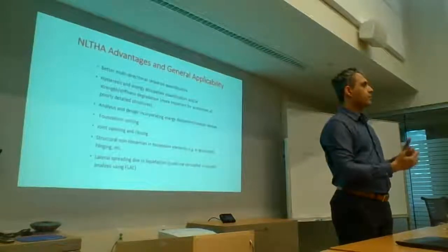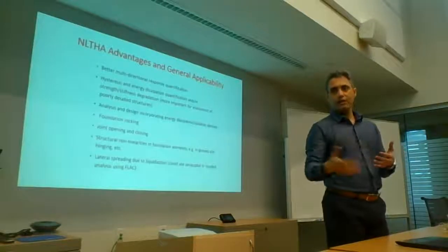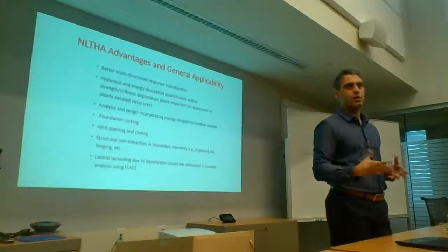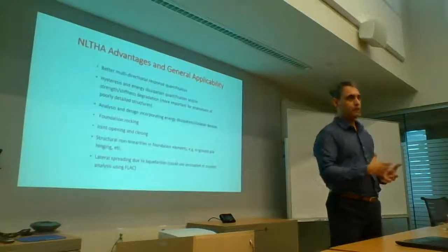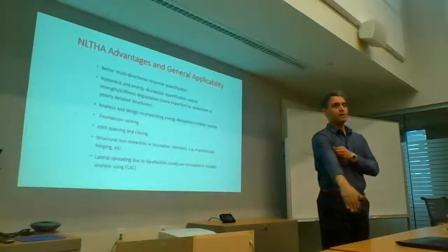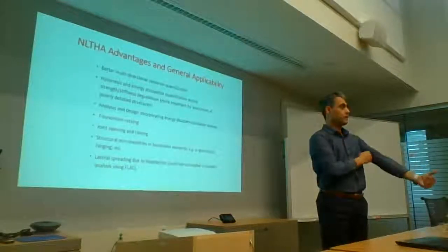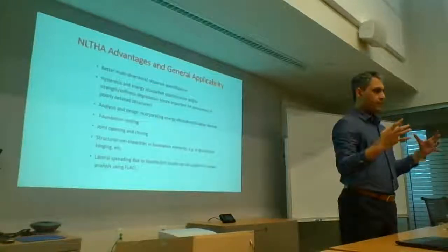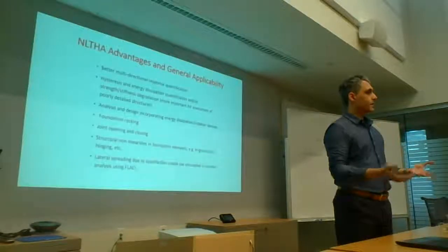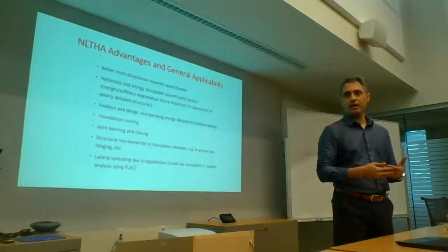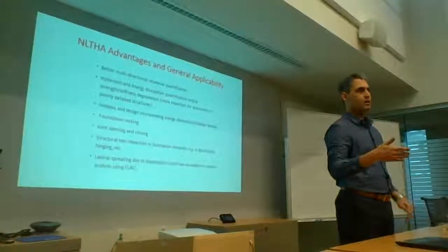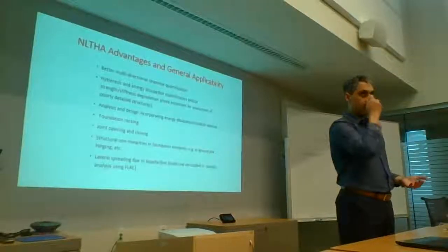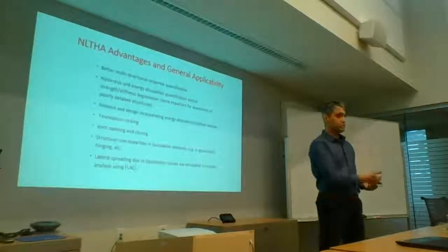And a lot of the times, the way to circumvent this is when you're doing new design, you are going to detail those things so that a lot of those issues just do not appear. Those things are suppressed. However, when we're looking at older structures, it becomes more meaningful to account for a lot of those things. But if you're finding early on that those deficiencies are extreme, then again, running a nonlinear time history analysis with the nth degree of precision is not very meaningful because you are going to see failure. Then you're better off thinking about how you're going to retrofit it.